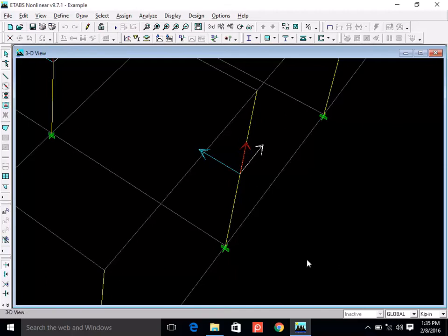But how about this axis? Look, this column has like 15 feet tributary area on one side, but on the other side, outside, there is no load. So all the load is on this side, which is actually, when you calculate the resultant, that would lie somewhere here. So that is an eccentricity, and this column will definitely have moment about this axis, but no significant moment about this axis. It means this is a uniaxial column.